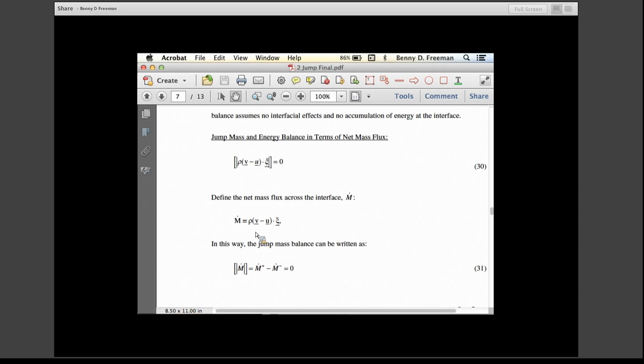You might think that it's just the density of the gas times the gas velocity, or that component that's perpendicular to the surface. However, if we imagine this as a glass of water, essentially, that's half full, and the water is evaporating into the gas phase, I can pick the glass of water up and raise it or move it, and that shouldn't be included in the net rate of evaporation of water from that surface.